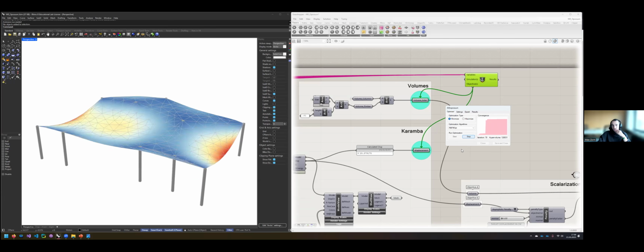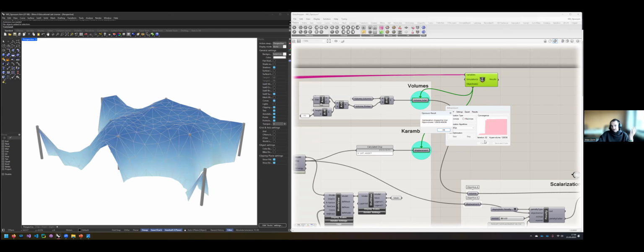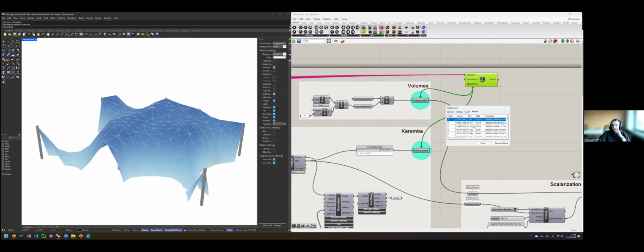Yes. Okay, cool. For demonstration reasons, I'm just going to quit it at 80 now. And what also changed now is the way the results tab looks. So it gives you the rank, it gives you a value that is called volume, giving you the objectives, objective 1 and objective 2, and the associated parameters. The rank is the Pareto front. So earlier, when I drew the Pareto front, right, the best front is the front with rank 0. It's where really all the best points are. Then the second best front is the rank 1, and so on and so forth.